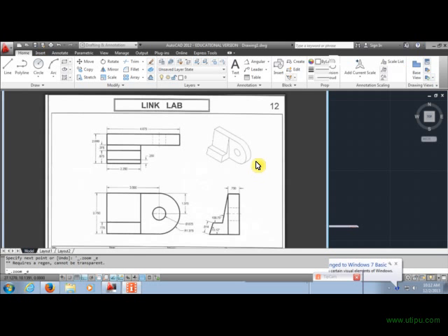And remember that while you're creating it, before you hit enter, once you've typed your number, you can always hit F5 to rotate through the directions of the isometric if you need to change which direction your ellipse is pointing. But in this case, we're just fine with it as is. So the next thing I'm going to do is trim, which is the same as it usually is. You can do the TR, and then you can either do the regular method or I'm going to do the shortcut, which is just the enter, enter. And I'm going to click this little section, and this little section, and then this section. Of course, because I cut off the other two sections, I need to actually erase this section.